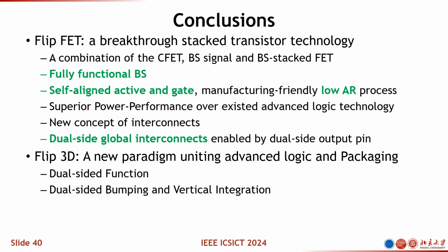And because of the self-aligned feature, the process of the FlipFET is actually much easier compared with the monolithic CFET. And the other thing I want to mention is the interconnects. You have the wafer front side and you have the wafer backside. So this would open a totally new regime for transistor stacking and also transistor interconnecting.